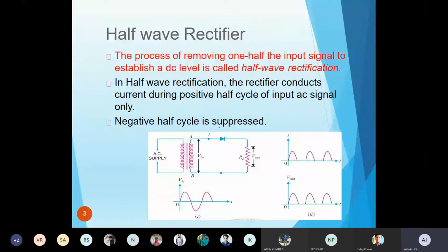It will be open. So you are giving the AC signal, which has the positive as well as the negative half. During the positive half cycle, the anode will appear positive and the cathode will have negative voltage, so the diode will start to conduct. During conduction, I told you that it will act as a switch. So the circuit will be like this, I will draw it here.